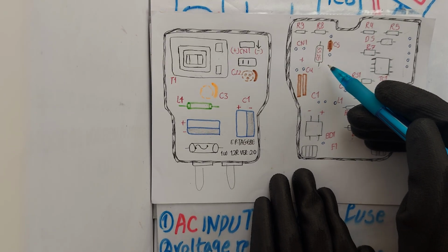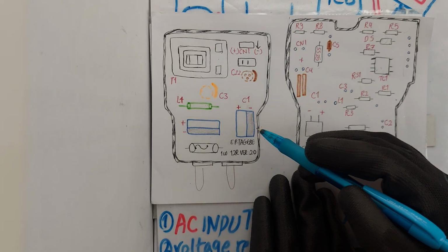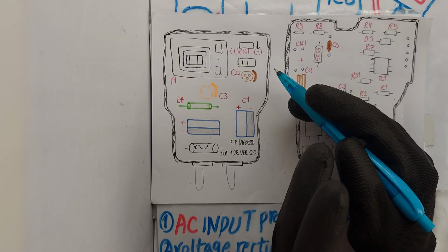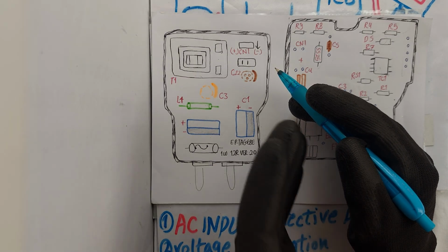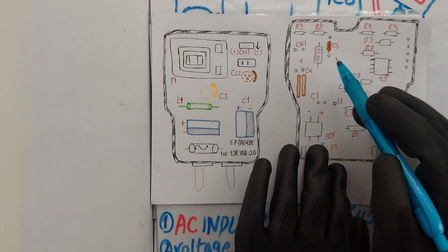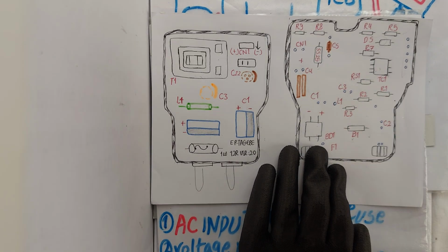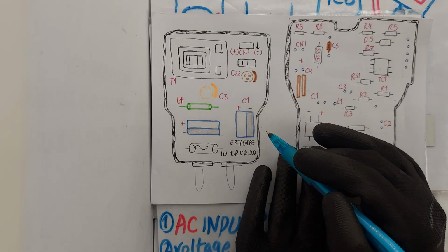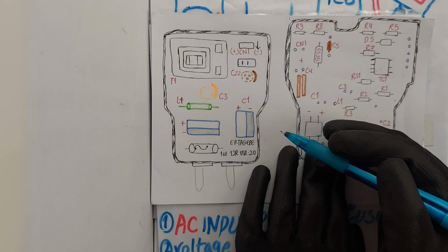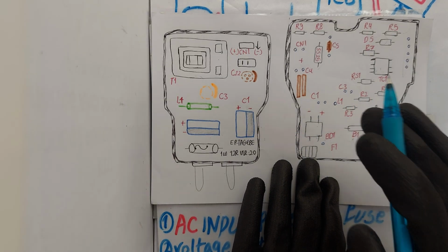Then an LC filter, inductor L1 and capacitors C2, C3 and C4, removes high frequency noise and ripples, stabilizing the output voltage. Many circuits use Schottky diodes with short recovery times to reduce switching losses. Capacitors store excess energy when the switch is on and deliver it to the load when the switch is off, keeping the 5 volt output voltage stable.